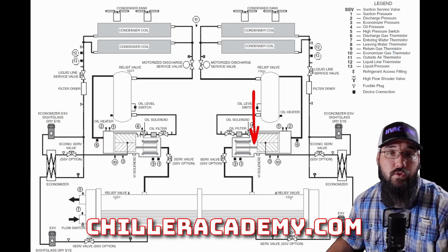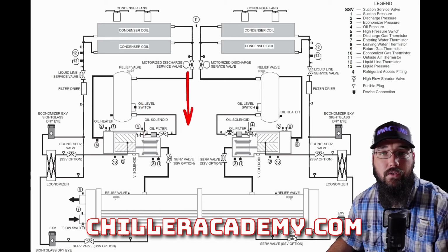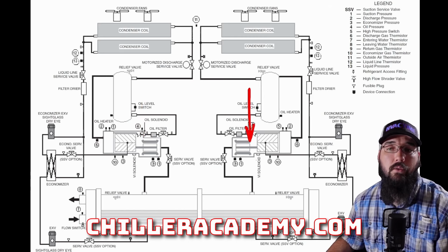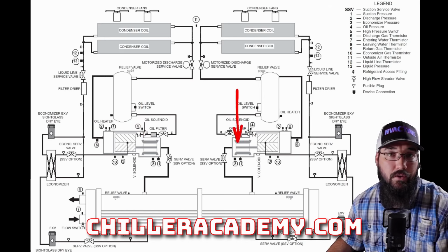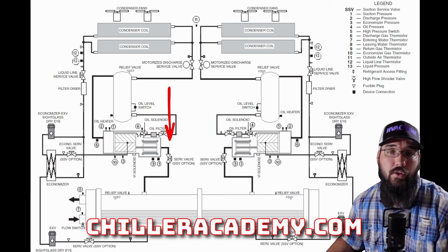Compressor 2 will just stay at full load. It'll start compressor 1 and start to bring it in and load it. As compressor 1 is coming in to load, it will start to back down compressor 2, and eventually it will try its best. The two of them will eventually meet in the middle in terms of how much they're loaded in trying to produce cold water.